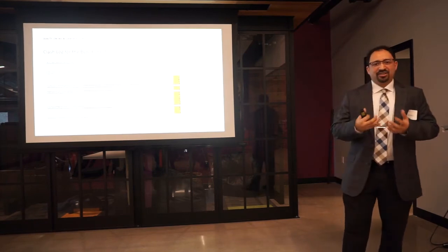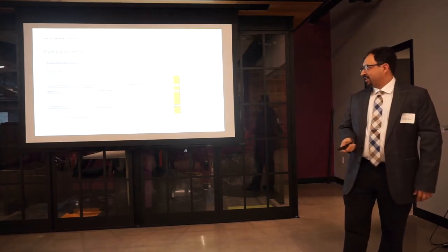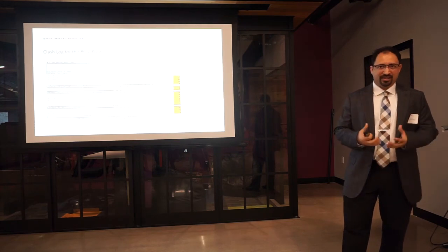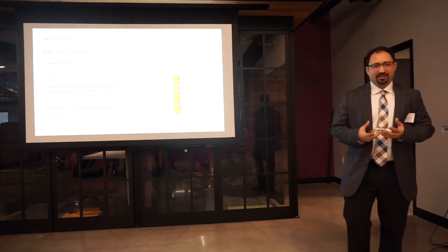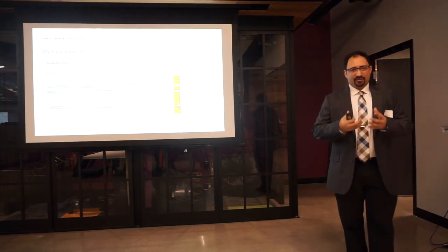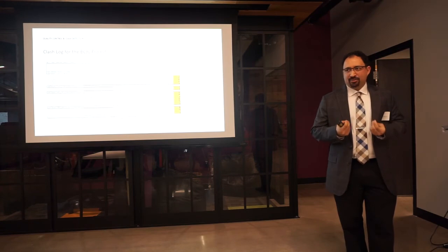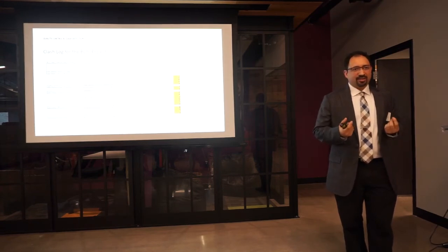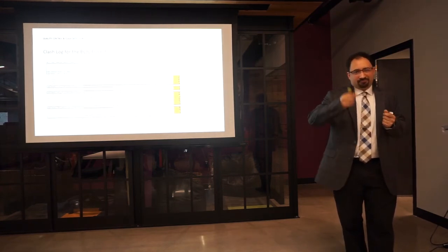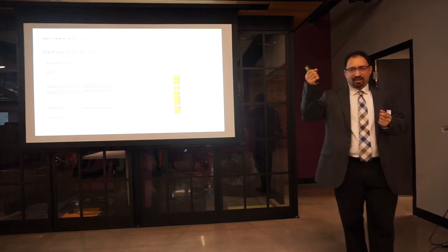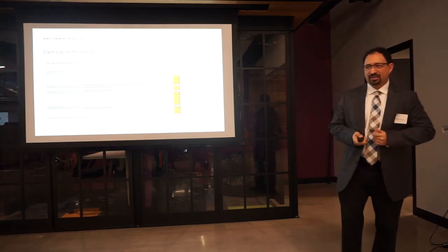Eventually we found our balance and we were able to finally reduce our clashes down to about 256, which were found to be on-field coordination items that we could not resolve in the model, such as we had a lot of hanging cable, pendant lights in our project that would require slight twisting of the cable to make it work versus a duct.